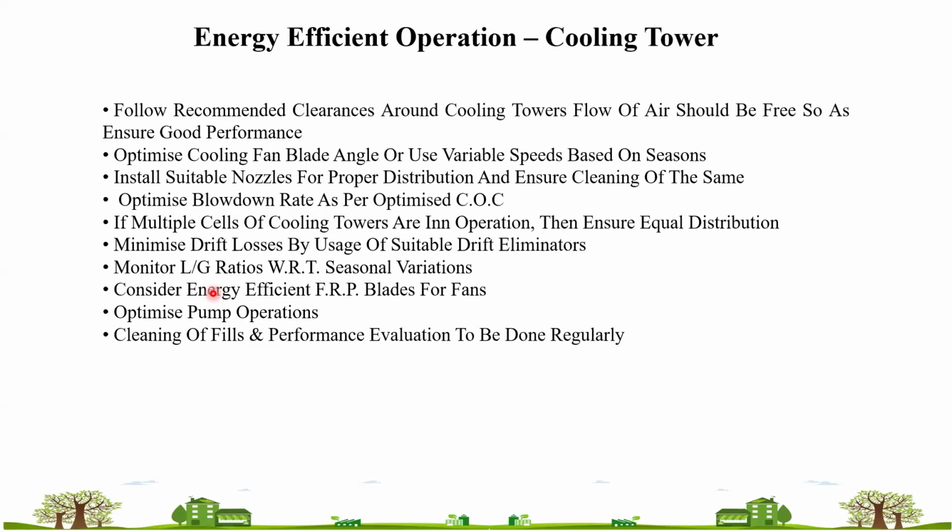Then what are the energy efficient operations of cooling tower? What are the recommended clearances? We have initially seen that people have to ensure the placement of the cooling tower is very critical. In the corner, in the area where no access is given, or somewhere behind the wall, or somewhere near the basement, cooling towers are provided. So that recommended clearance has to be there. There has to be some free air flow from the near side of the cooling tower.